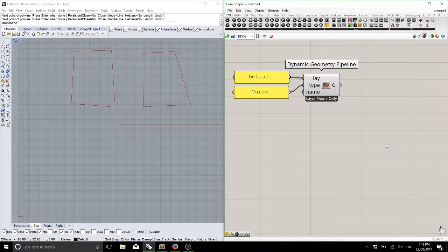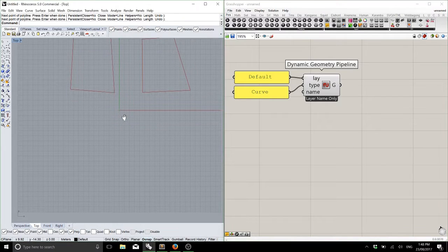Okay, so is everyone clear? We've got 2 polylines coming into our system. Now, Grasshopper's super dumb, right? So if I drew this curve, it's also going to pick that curve up. But is there a problem with that curve versus what I've drawn? It's open, right? Now, do we want to rely on us to be diligent and never draw an open curve? Or do we want to write into the script a check?